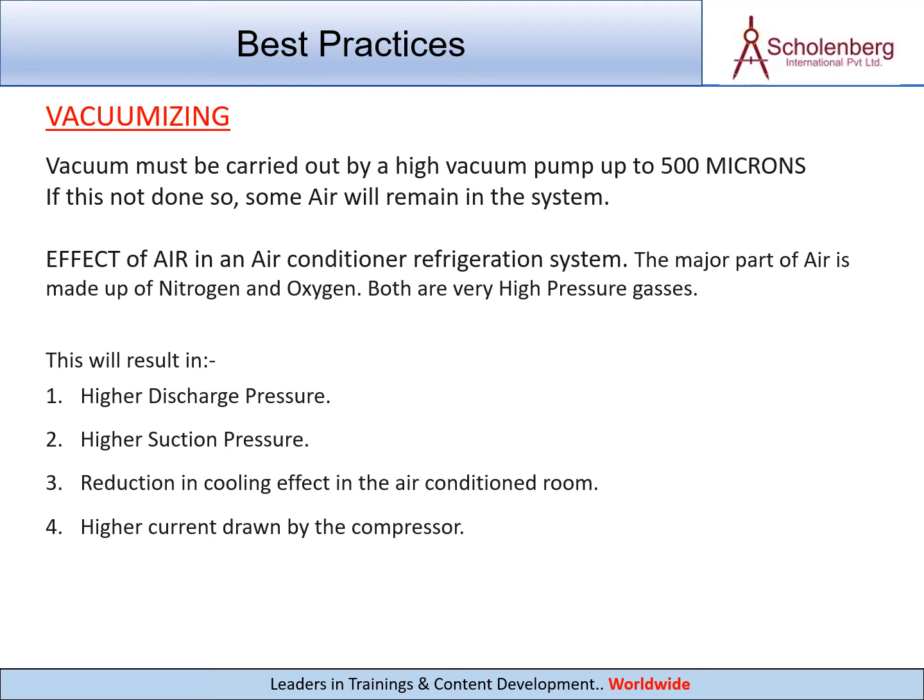This will result in: 1. Higher discharge pressure. 2. Higher suction pressure. 3. Reduction in cooling effect in the air-conditioned room. 4. Higher current drawn by the compressor.